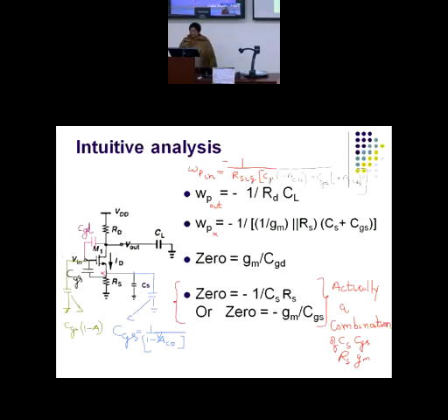Then you come to the node X and find out omega Px. Again find the time constant at this node. So here we have a CGS component connected. Here we have RS. There would be certain parasitic capacitances appearing at this node and ground, which I am calling, say, CS. So if you break CGS, you will get a component at the X node. And what's the value of that component?